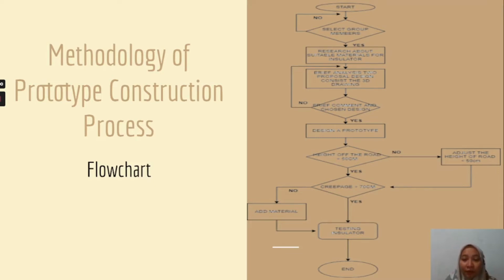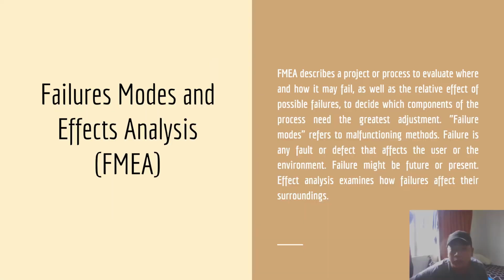If more than 50 cm, we need to measure the creepage. If the creepage is more than 70 cm, we can test the insulator. If no, we need to add material. That's all my part.